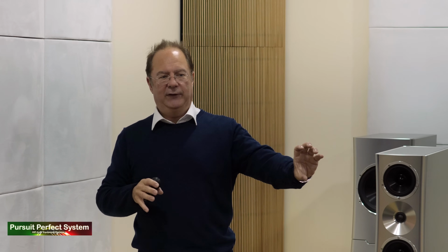As time has gone by, the algorithm has improved, tap length has increased. I changed the algorithm, and the algorithm is all done by a mixture of two things: theoretical knowledge about what's going on when you're using an interpolation filter, about trying to reconstruct the transients as accurately as possible with a finite amount of processing, and more importantly, listening tests. Everything is done by optimizing with listening tests. And there's been hundreds and hundreds of different listening tests to try to make this WTA filter more accurate in reconstructing the timing information. What I ended up with was a 256 tap length WTA filter that sounded better than a 2048 tap using a conventional algorithm. So I got a 10-fold improvement in how it reconstructs without increasing the tap length. So that's really important.